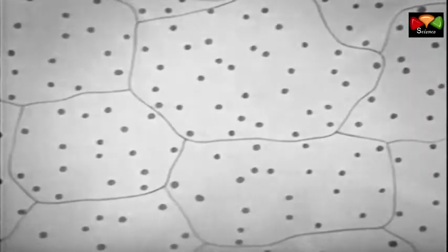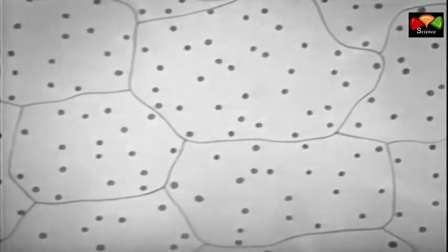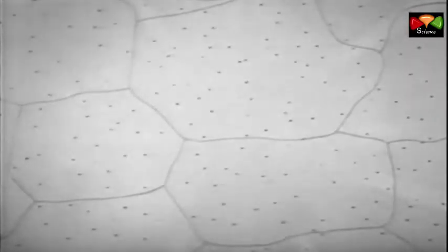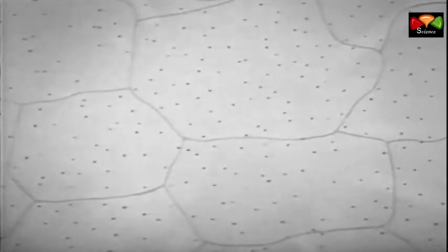The solution heat treatment of an aluminum alloy, such as 24S, involves the further dispersion of the alloying element throughout the aluminum in minute particles and, following a rapid quench, the precipitation out of solution of some of the copper in the form of fine submicroscopic particles of copper aluminum compound.